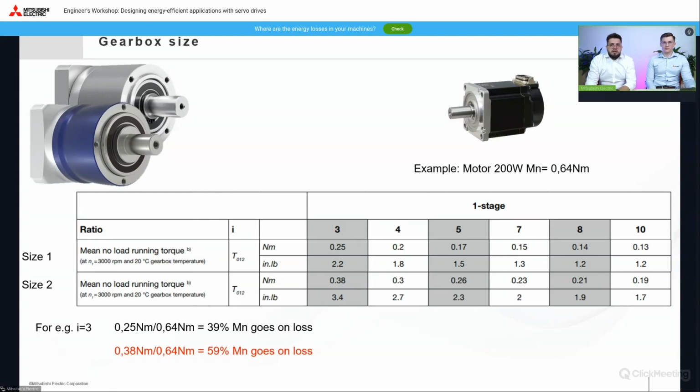And that aspect is terribly often overlooked during the sizing, which in extreme cases can cause the servo to overload because it's not able to achieve the cycle performance, and the internal resistance of the gearbox is too high. Yes, it's too high to drive the motor even.